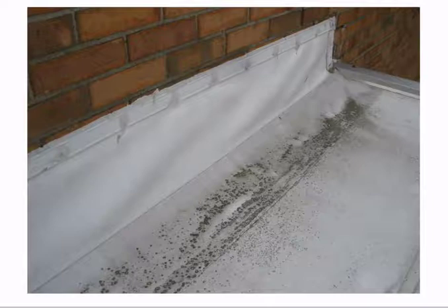So if we're looking at a common occurrence in roofing, Craig, back to your roof here where we've got the base flashing coming up, being terminated with the raw plug fasteners hammered into the masonry. Here, we're relying strictly on that top bead of sealant to maintain the waterproofing integrity. So there are other things that want to be tightened up here, but sure, a contractor could just replace that sealant if it's leaking, no question.